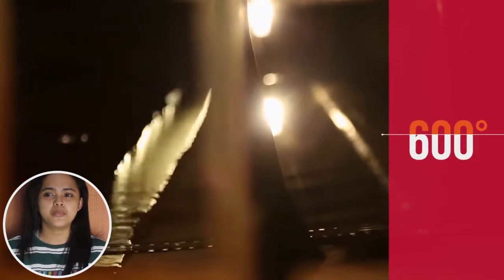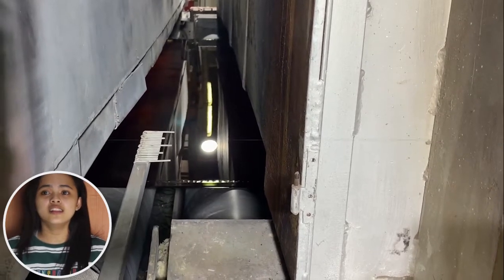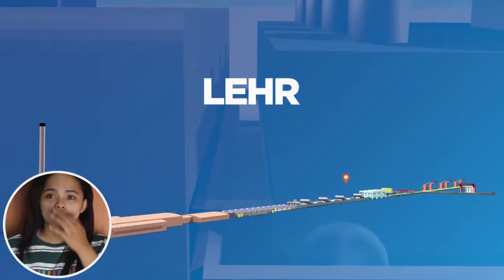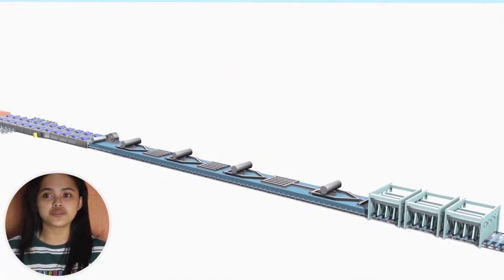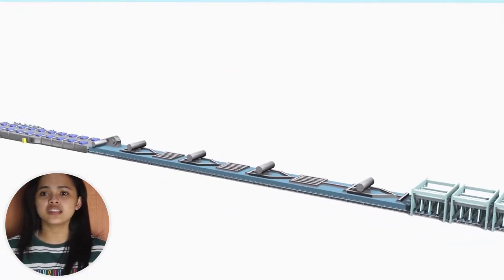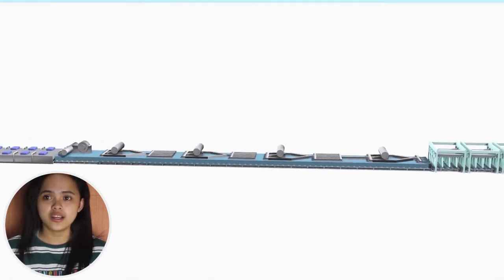At the end of the float bath, the glass is cooled further and leaves the tin bath at around 600 degrees Celsius, when it's just solid enough to clamp on the metallic rollers and be driven inside the lehr. In the lehr zone, the glass is annealed and gradually cooled to relieve inner stresses and prevent splitting in the cutting phase. Cooled down too quickly, it would break.